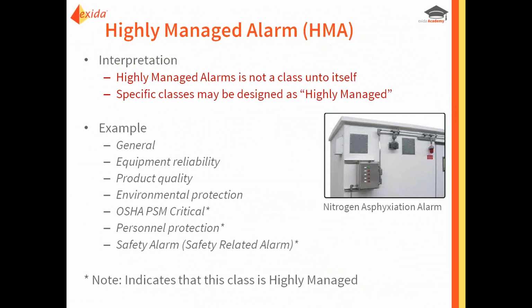So also to prove that it's going to work, you may test it very frequently, every week, every month, to test to make sure that that alarm will go off when it's required or when it's needed. Also want to make sure everybody knows when they see that red light blinking, operators and everyone should be trained that you don't go in that shed if that alarm is going off. So in this case, there's an alarm that requires a lot more testing, training, and thought than your average process alarm.